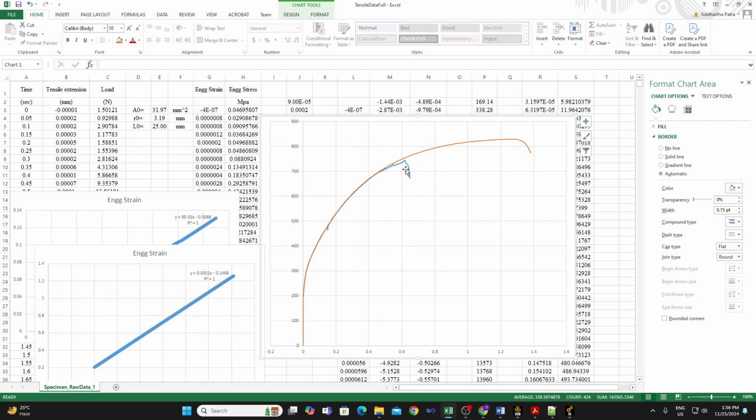That has gone from 0.6 to around 1.3. So the total strain over here in the experimental data is 0.6, whereas in the simulated curve, it is 1.3. That is simply because the actual material is rate dependent, and beyond this point it has reached a strain value where it starts showing the serrated behavior. So it essentially shows type A serrations over here.